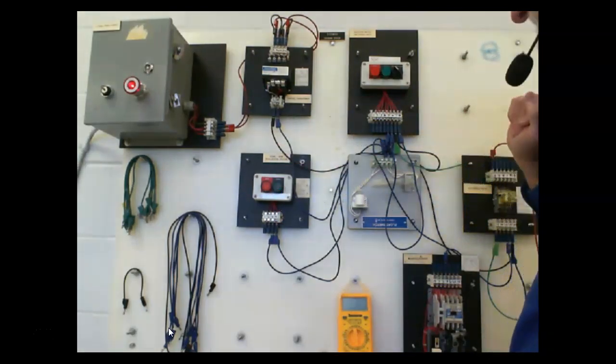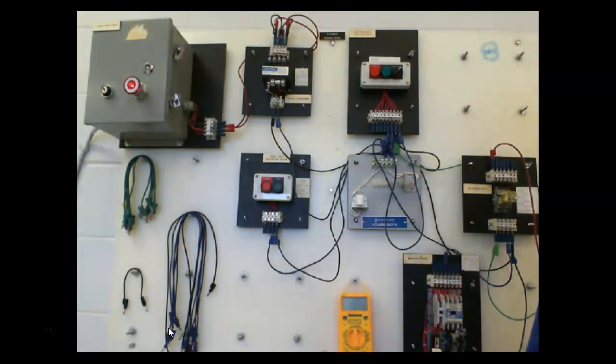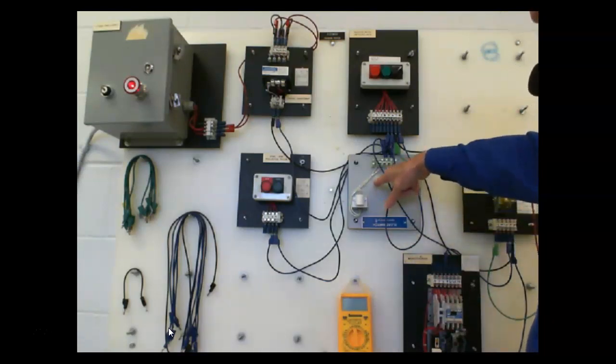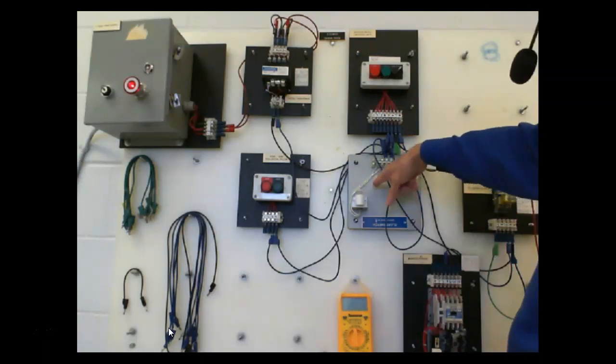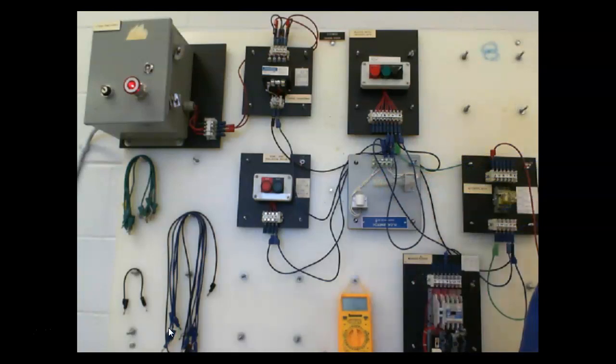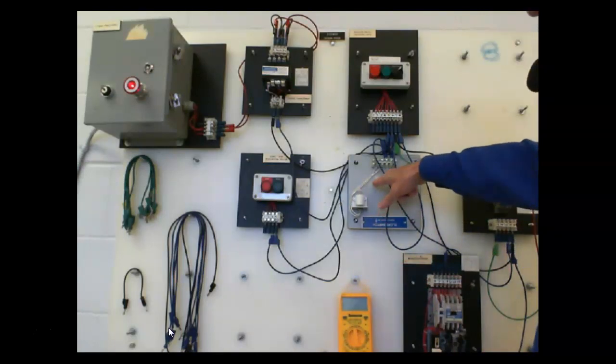Hear that, James Roy? Okay, so this is auto. So in auto, it came in instantly, which is telling me my tank is empty. So we started off with our tank empty, right? This is a charging system. I'm sorry, so this would be tank full. So our tank started off full. And then when it gets empty, because this is a charging system, I said that wrong. When the tank gets empty, the liquid level switch drops down and turns the pump back on, fills the tank back up. When the tank gets full, you'll see this.